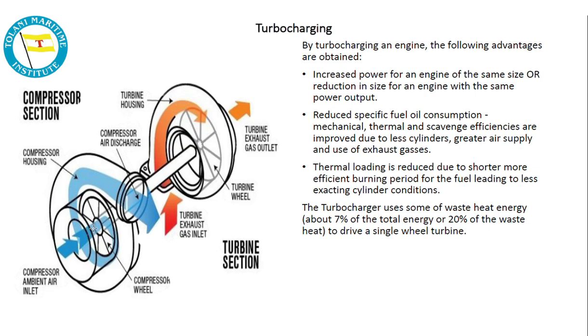Air is drawn axially into the center of the impeller with radial blades and is pushed radially by means of centrifugal force. The rotation of the impeller accelerates the speed of air and forces it to pass through diffusers and volute. Here high kinetic energy is converted to pressure energy, slowing down the speed of air through expansion. Now you see everywhere the curvature getting expanded. From here it increases here.